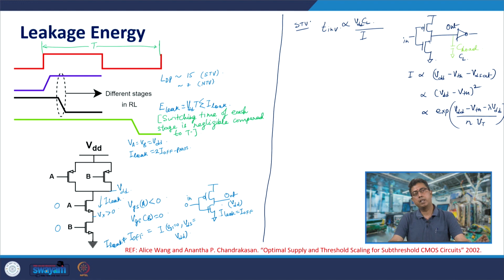In other words, the value to which the output capacitance needs to be charged, or from which it needs to be discharged, reduces, and similarly the current also reduces almost with the same factor or with a somewhat larger factor. If it is pinch off related saturation, then the reduction in current would be faster, but it would not be significantly faster.